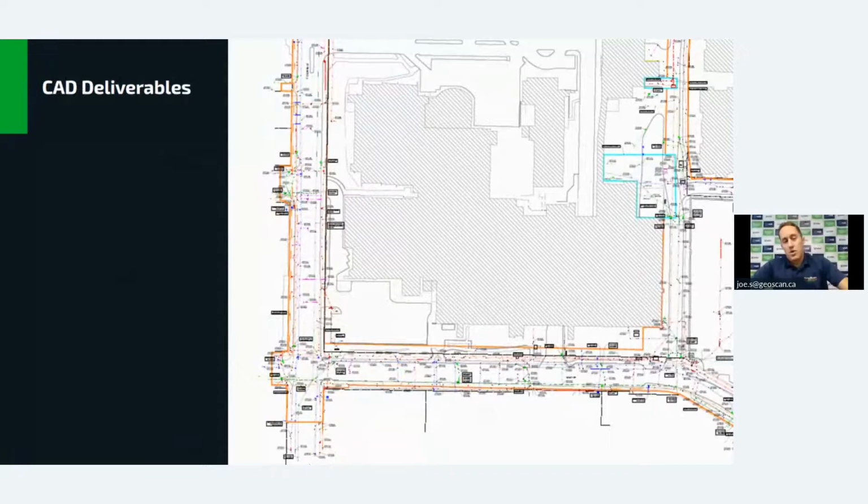So those reports come as standard, and if you're looking for something more technical and permanent, we can produce CAD, AutoCAD deliverables, and also GIS deliverables. And these are created by surveying, either using total stations or GPS, surveying the marks and then plotting them out on CAD or in GIS.